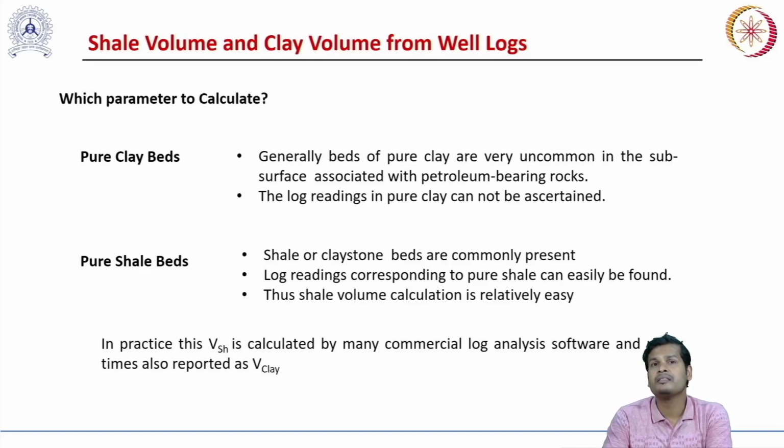And we know that clay contains bound water and also hydrogen as a part of its chemical structure. So hydrogen is present inside the clay in the bound water and also as a part of its chemical structure. But this hydrogen is not related to any mobile water. Whatever hydrogen is there in the bound water or as a part of the chemical structure of the clay is not mobile. So this hydrogen should not be taken as an indication of mobile water or the pore spaces occupied by mobile water molecules.